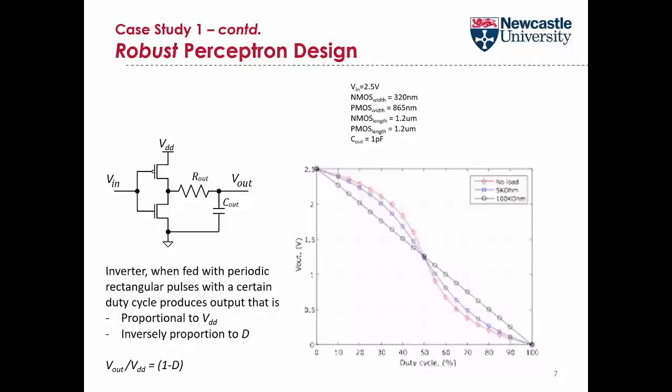So then what we did is, unfortunately, the legibility is very poor, which is very unfortunate. I don't know why. What we did is we tried different configurations of this inverter, with or without resistors. As you can see, with resistor and without resistor, we have a bit of skew in the duty cycle. As you increase the duty cycle, this is an inversely proportional relationship, so the output will be decreasing almost inversely proportionally and linearly. That is the expectation.